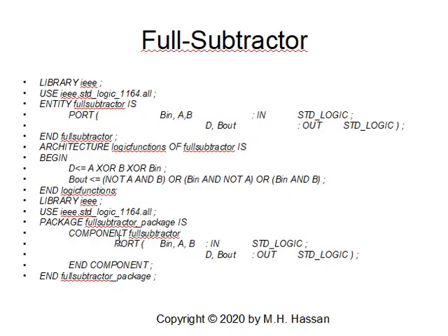The full subtractor, the same thing, just the equations have been defined separately. And I will package the full subtractor after the code. See, I am showing you as an example that the packaging could be done within the entity name full subtractor. So full subtractor will be defined by borrow in, A and B, and the difference D and B out.